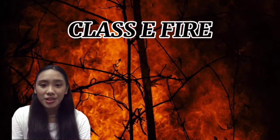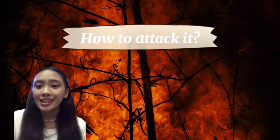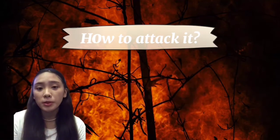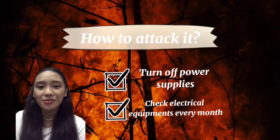Fifth would be electrical fires. Electrical fires usually start in unchecked or damaged live areas. In attacking an electrical fire, you can use carbon dioxide or dry powder in low voltage situations, but always remember to turn off your power supply first. Monthly checking of electrical equipment can help to reduce the risk of this type of fire.